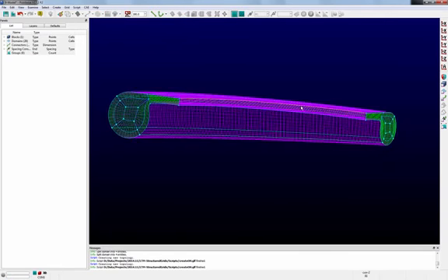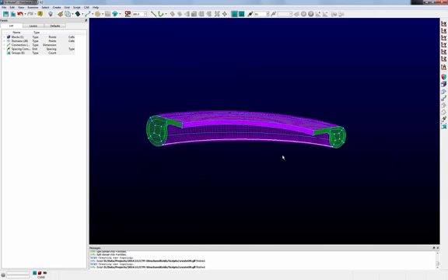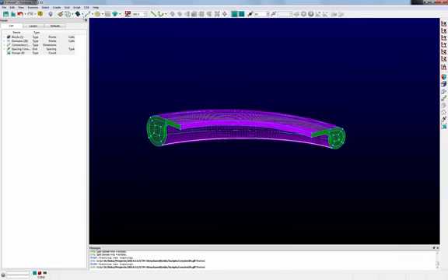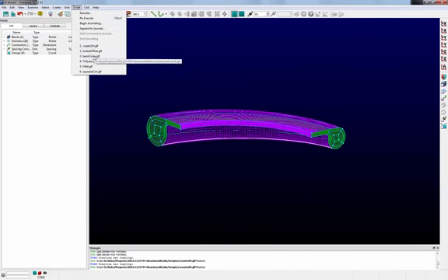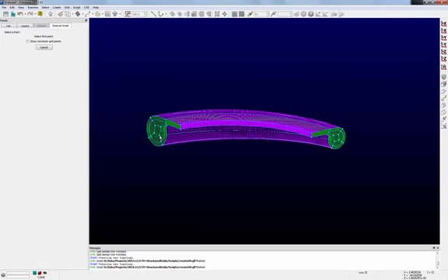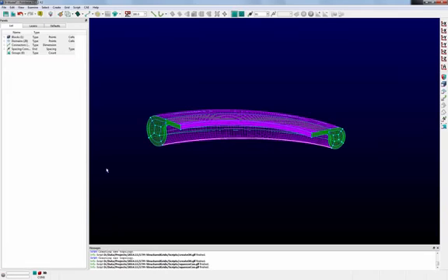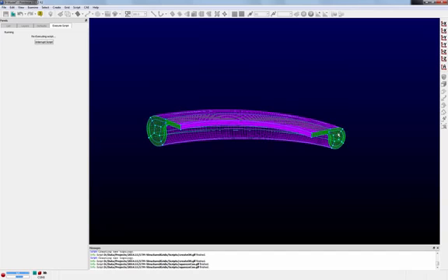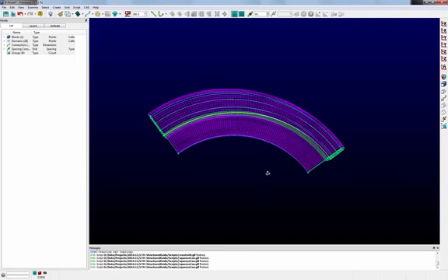Unfortunately, we can't just highlight these and generate our blocks directly because Pointwise doesn't know about that inner H block. So we need to create the topology there as well. But we can use that squeeze connector script that we used earlier to translate and scale these connectors on the outside edge to fit between these points. So I'm using this bottom connector here, and then I'm just clicking between points on that inner H block, the corners of that inner H block, and then we've created that inner topology.